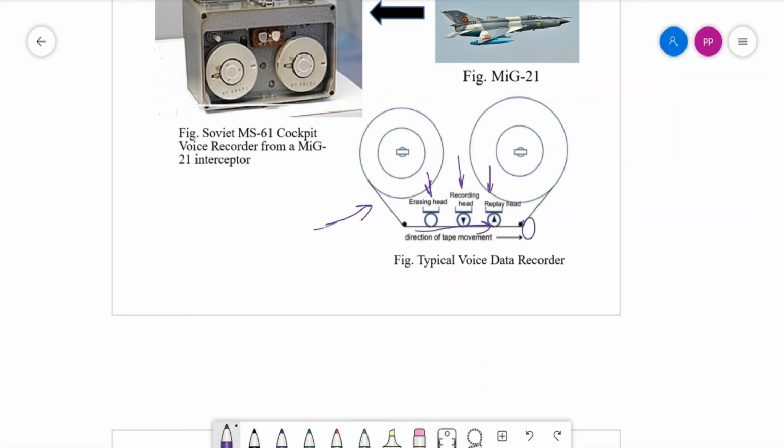That will control the speed of the movement of the tape. Because if we don't have the pinch roller here, because of the change of radius of the driving motor, the speed will change at this end in front of the head. That is not advisable. You should have the tape moving at a constant speed, so you are using a pinch roller.